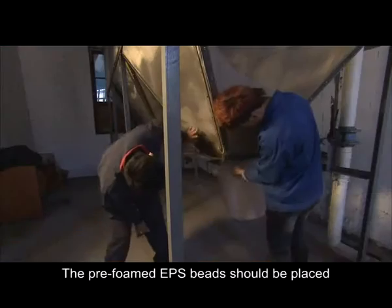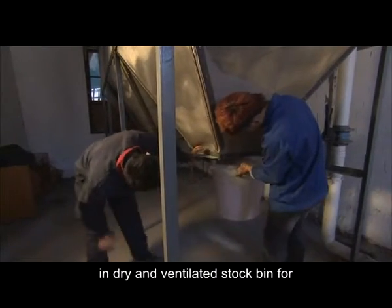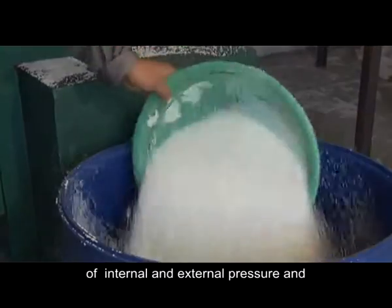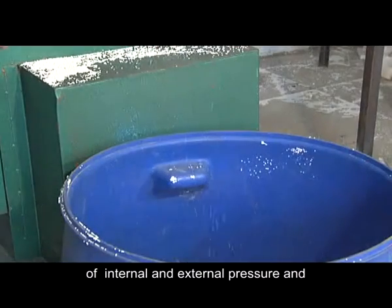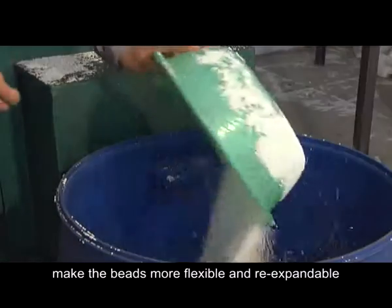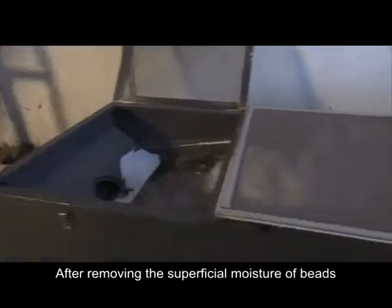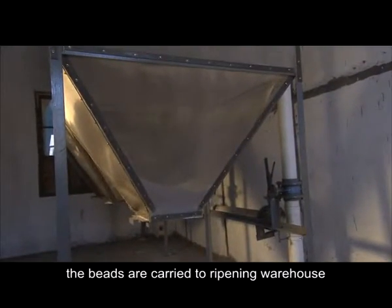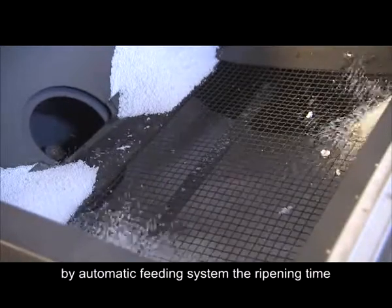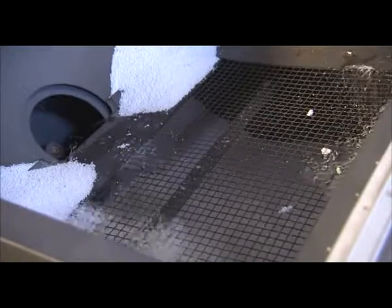Ripening. The preformed beads should be placed in a dry and ventilated stock bin for a certain time to maintain the balance of the beads' internal and external pressure and make the beads have flexibility and re-expanding capacity. After removing the superficial moisture of beads, the beads are carried to the ripening warehouse by automatic feeding system. The ripening time is about 8 to 48 hours.